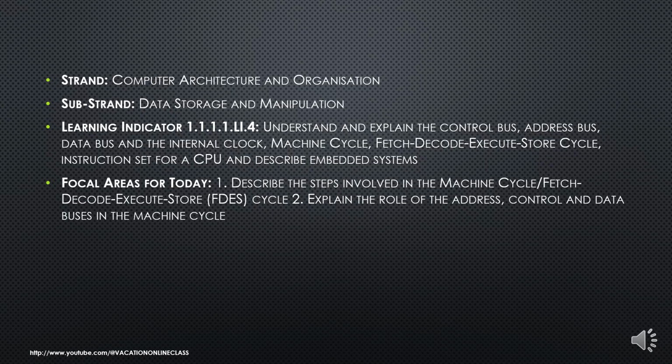Focal area for today: describe the steps involved in the machine cycle, fetch, decode, execute, store, that's the FDES cycle. Explain the role of the address, control, and data bus in the machine cycle.